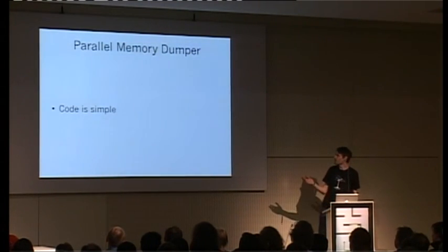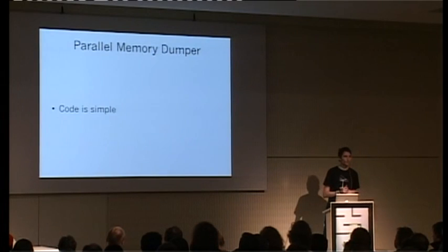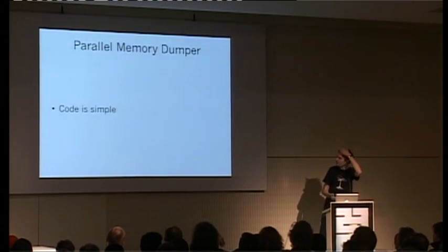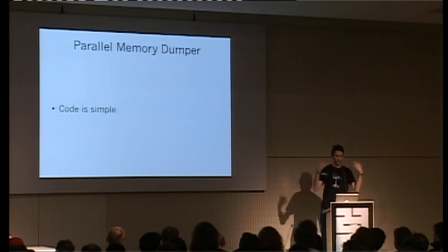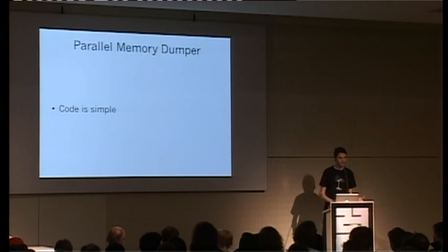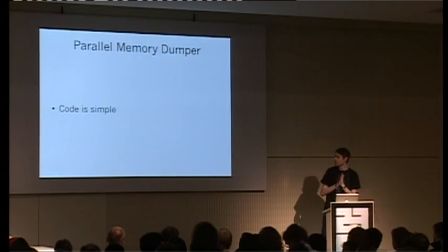I should also mention that flashrom.org has a whole infrastructure. I don't think they deal with parallel flash, but they do deal with like NAND and stuff like this. So they also have some support for microcontrollers to dump memory. So there should be no reason that you need to buy an expensive programmer. You should be able to dump it on your own.